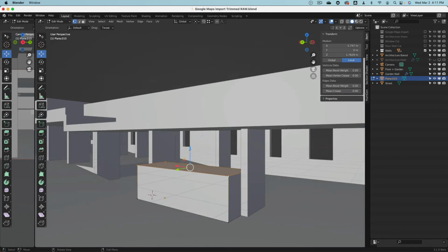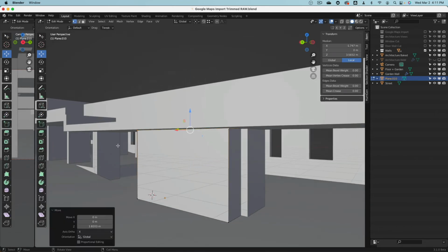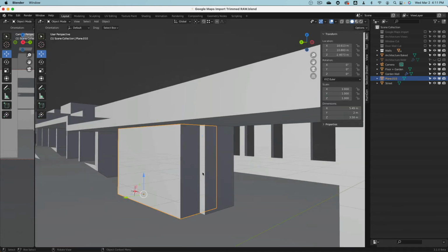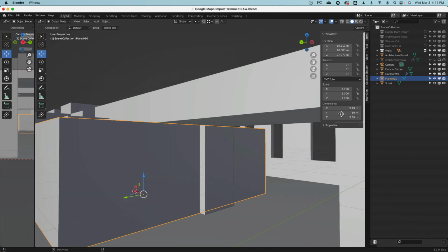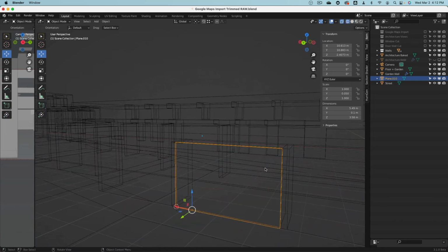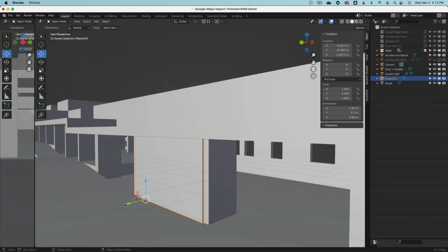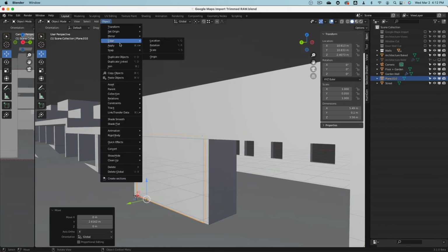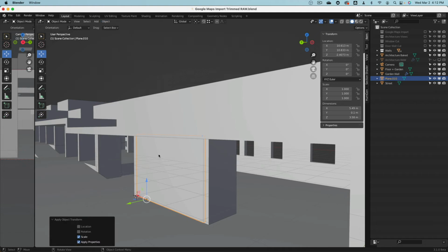Into not only one, but those 3 openings. So I drag this volume up. In object mode, I can see this is 3.58 meters tall. This is too much. Let's say 10. Whoops, not 10 meters, 10 centimeters. Okay. Very good. Push to here, push to there. Then apply scale and set origin to geometry.